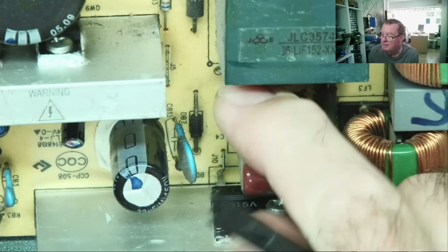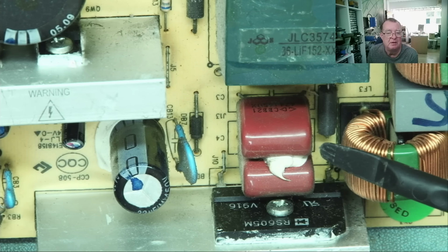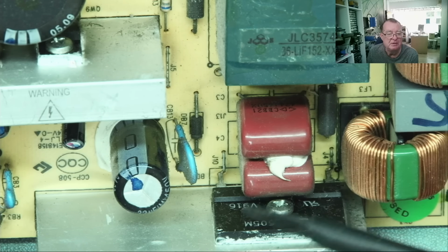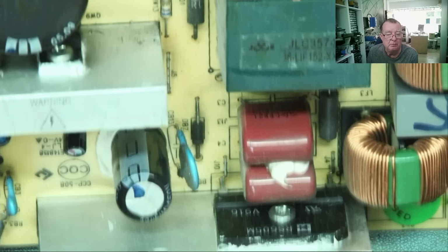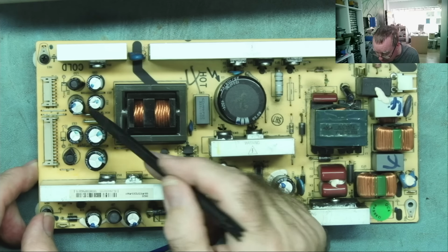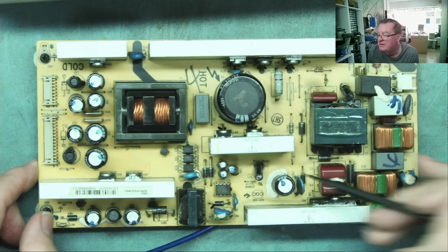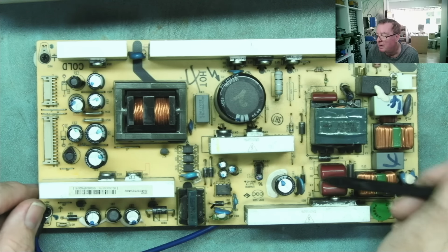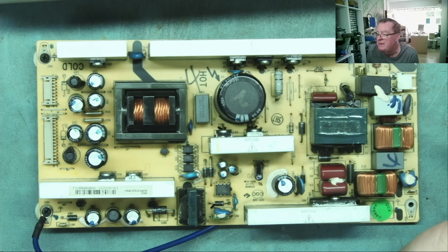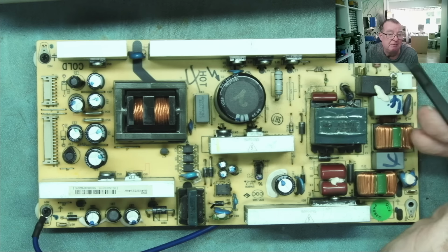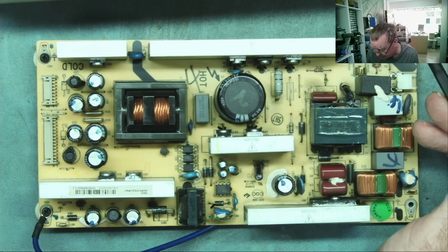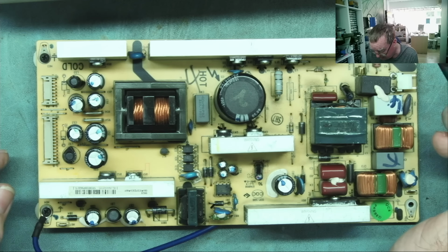They're also used, as I mentioned, in switch mode power supplies, in a circuit called an LLC circuit. It's again subject to high frequency switching, so they tend to fail. And when capacitors fail, these types, the electrolytics and those types, generally speaking, it doesn't damage anything else. So replace the capacitors and the fault will go away. Generally, okay, you'll always find exceptions, but generally speaking.